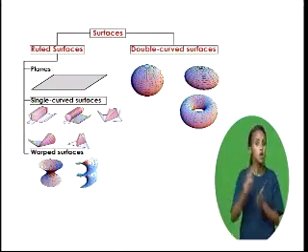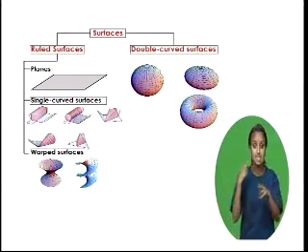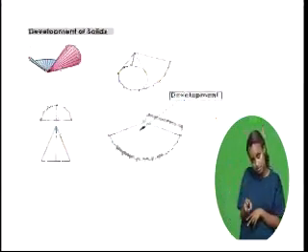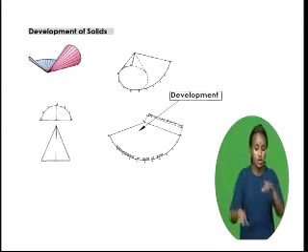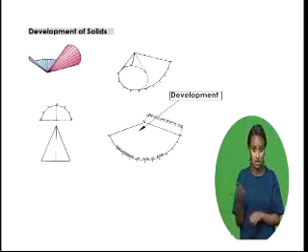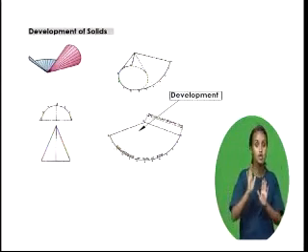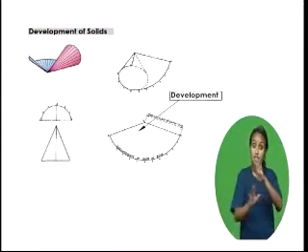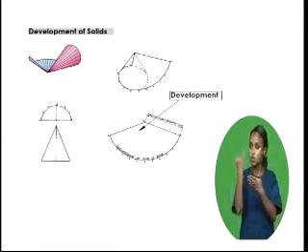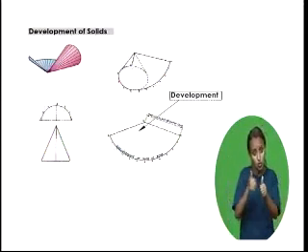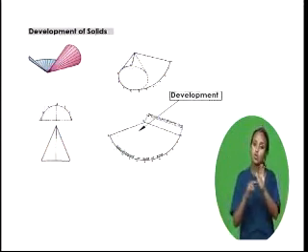There are two types of surface, namely ruled surfaces and double curved surfaces. When surfaces of an object are laid out on a plane, the drawing obtained is called its development. To make different items, a surface development is first drawn as a pattern. A drafter should follow certain general rules during the development of surfaces.